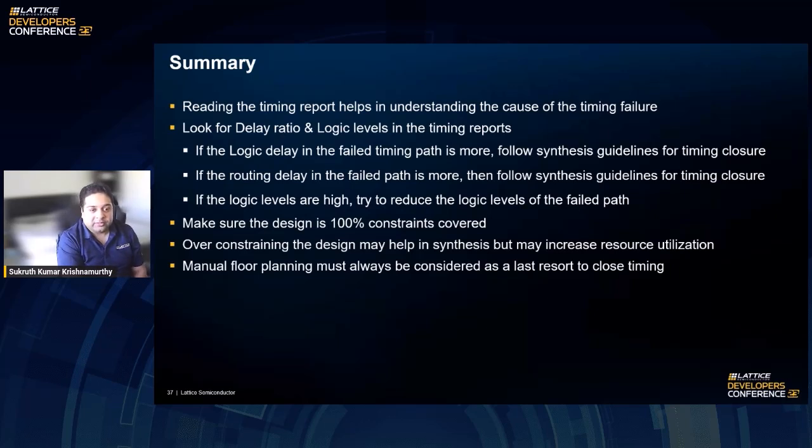Make sure that the design is 100% constraints covered. We talked about 3 sets of constraints that are needed to achieve 100% constraints coverage. One is the clock constraint, to constrain all the clocks in the design. The I/O constraints are used to constrain the input ports and the output ports. The combination of all of this will lead to 100% constraints coverage.